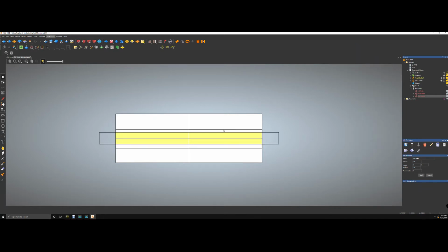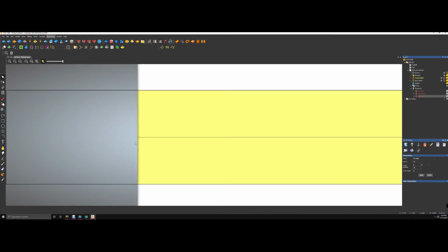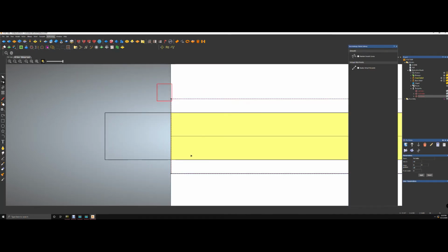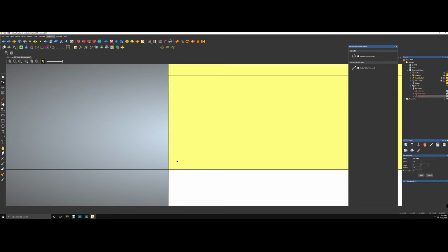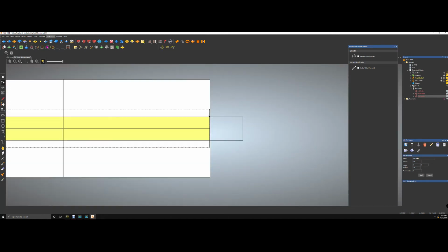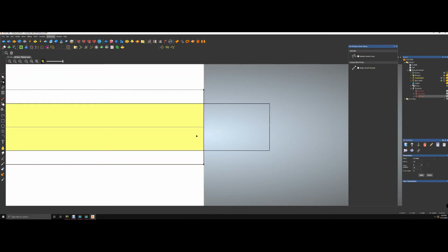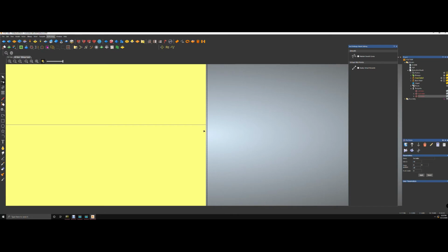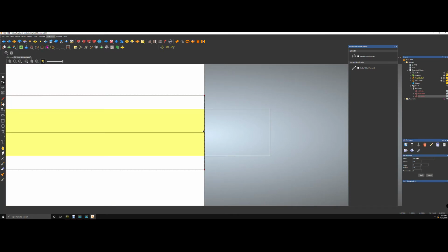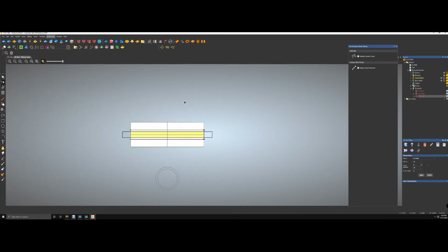Okay, and you make sure this is centered, F9. So if you want to check, you see how that's inside the model. So we're going to press N for node and bring it out so it's even with the model. It's very important you do that. Otherwise, you'll be milling nothing. You'll be missing some part of the model. So it's important to do that. If you want to go outside a little bit, that's okay. We'll just run empty before it drops onto the actual model.